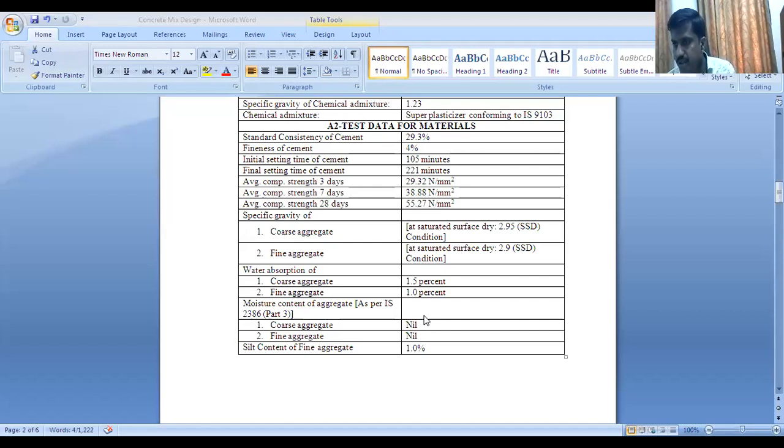after 3 minutes. I think in the theory part you haven't performed the practical on the field, right? So that is why you are unaware of this concept. Okay, I will tell you, don't worry about it. So when you add the water, you have to mix the cement with the water within 3 minutes only. Why within 3 minutes? Because after 2 to 3 minutes,